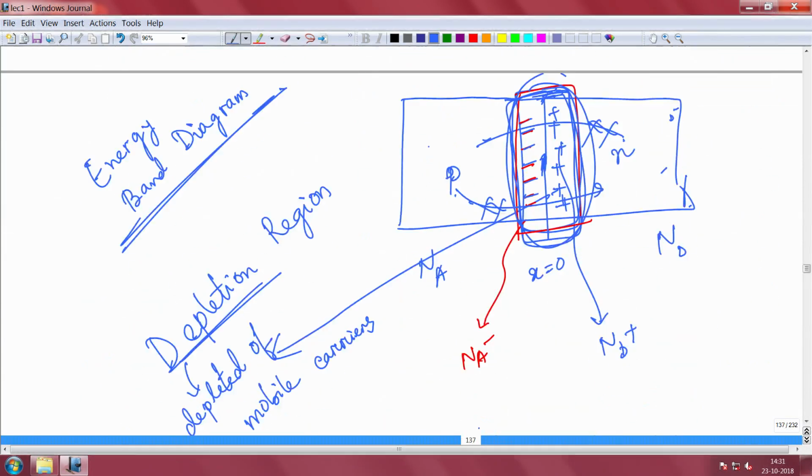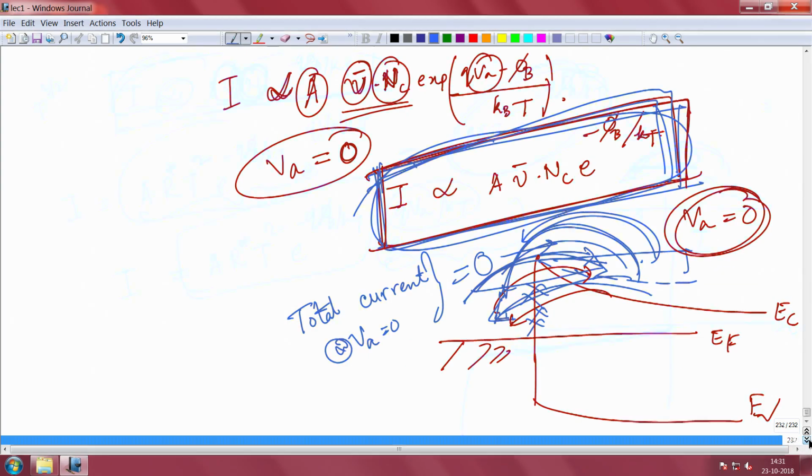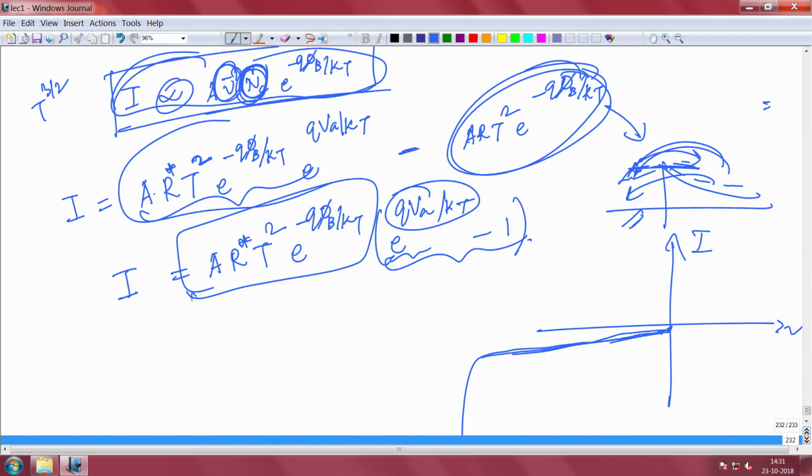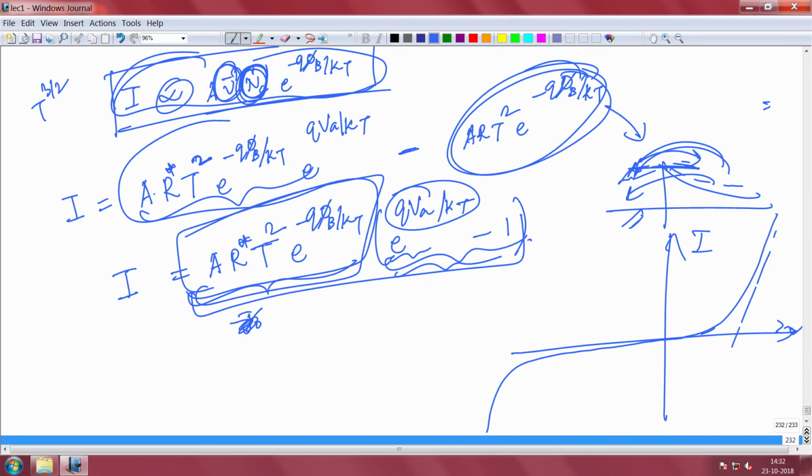In forward bias, you can see that this is the total current, which is exponentially dependent. So, the exponential dependence goes like this, this is 0 actually, sorry, just put I and V here. So, this will break down with very small current. This is the forward bias characteristic. It is an exponential increase, just like a PN junction, except that in a PN junction this is J naught, and in a Schottky barrier junction this is this. Another dependence is T square here. So, you see in forward bias you have the exponential dependence, and in the reverse bias you have a constant current given by this.